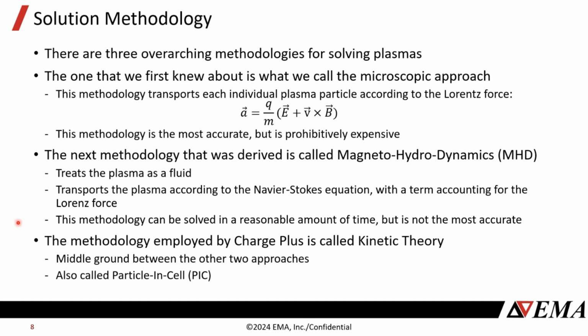And so there are problems with both of these two approaches, whether we're talking about computational expense or accuracy. And so Charge Plus adopted a method called kinetic theory, which tries to get to the middle ground between the two approaches that I just mentioned. This methodology, the way that we implement it, is called particle in cell, or PIC for short.